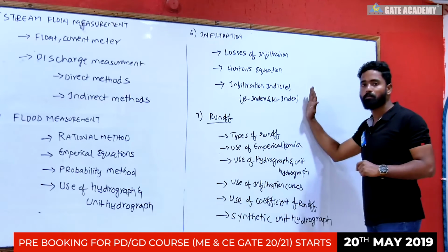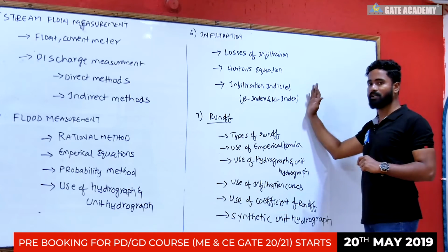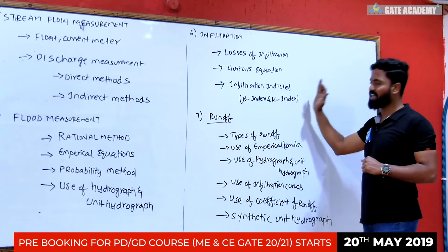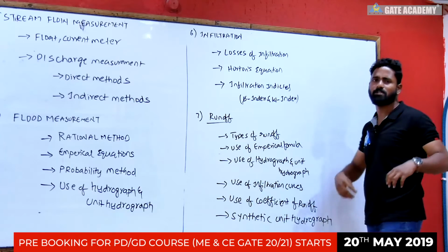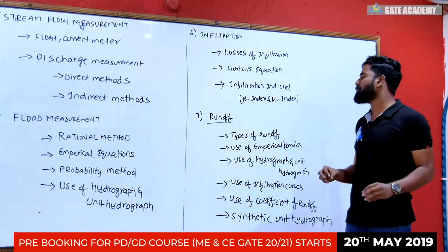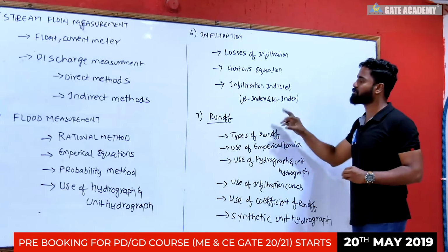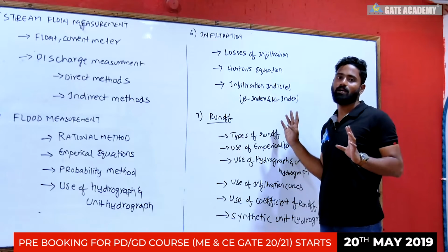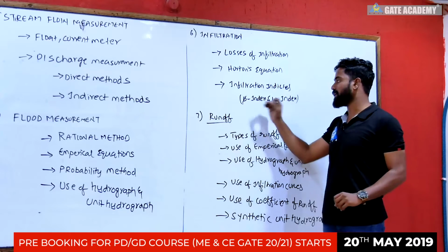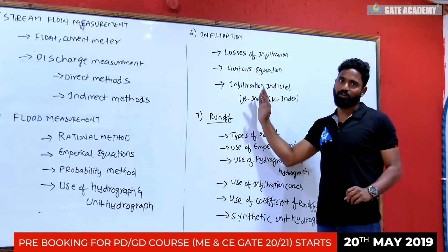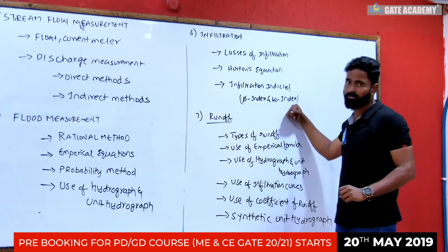Next comes a more important thing, infiltration indices. This is important from GATE, engineering services examination, state services examination, whatever the examination. Many times you will see a question based on phi index, W index, average infiltration rate. Phi index or W index is the average infiltration rate.